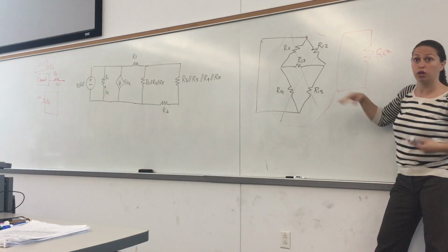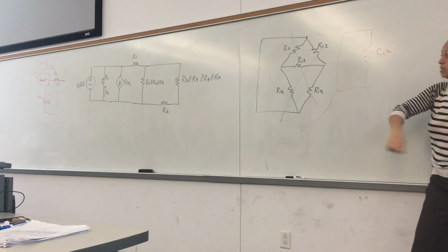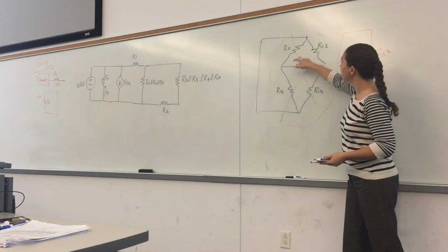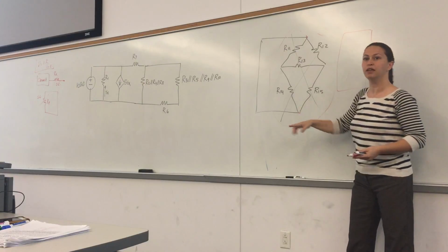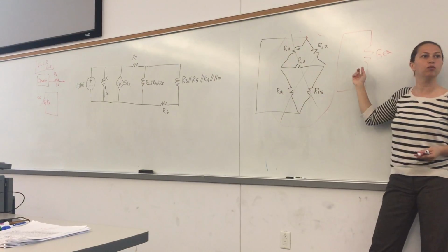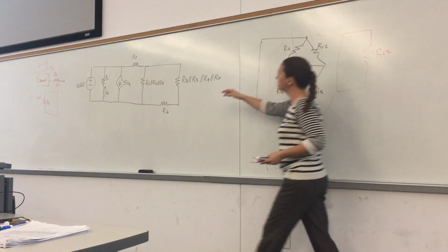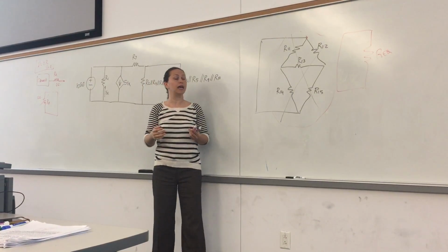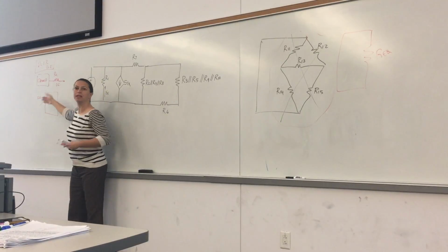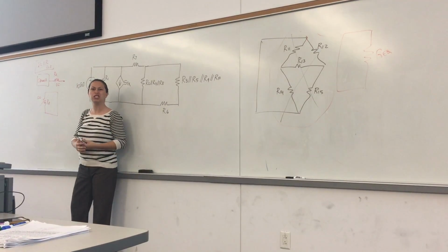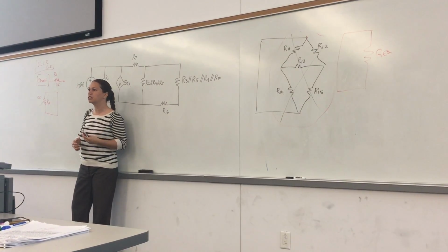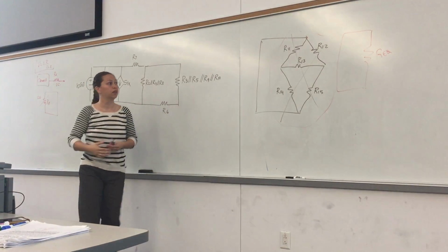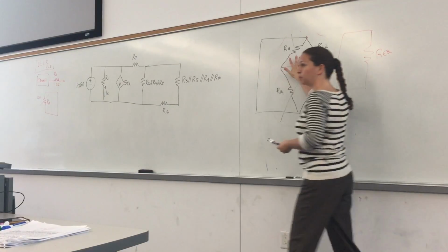Another way of proving that to you: last time, I numbered each of those wires, right? And I showed you that eventually, when you put them all together, this whole thing turns into an equivalent resistance that is in parallel with a wire, or you can think about it as a resistance that's floating. But in any case, it's just going to be a dummy resistance, which is not going to be affecting the solution, which means that you can ignore all 5 resistors.